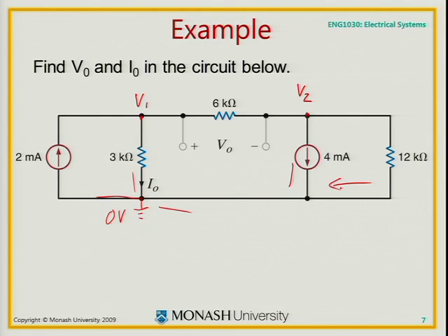So yeah, you're right. All you can do is apply Kirchhoff's current law or Kirchhoff's voltage law and use Ohm's law. You don't have any other choices. You've sort of just got to start. You could do a KVL around a loop, or you could do a KCL. So that is really the only choice that you have. But what nodal analysis says is, well, let's do that systematically. Let's provide this systematic procedure.